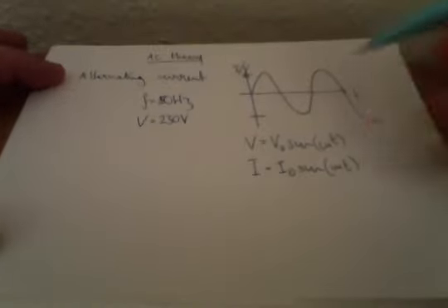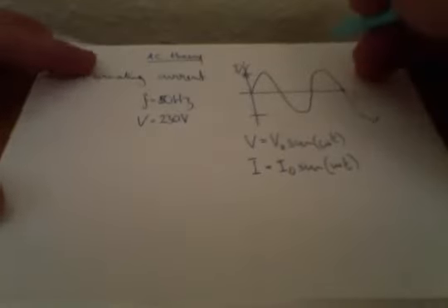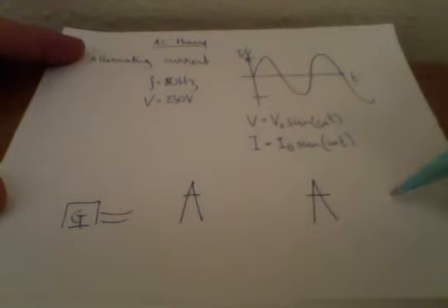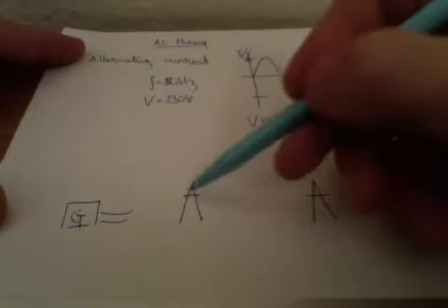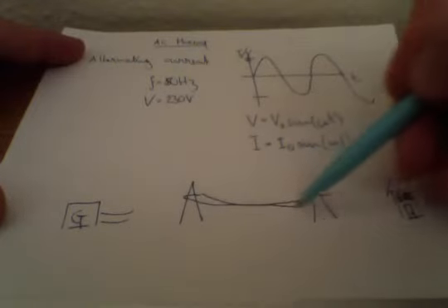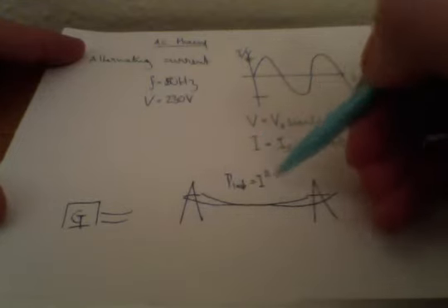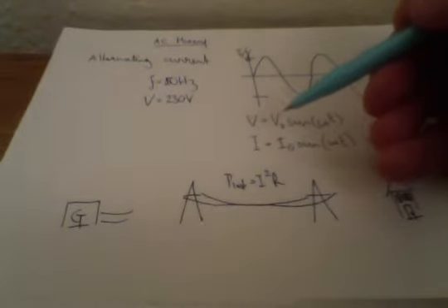Now there's a good reason as to why we have AC coming through, and I will quickly go through, now we have the facts down, why we use AC. Generators produce electricity for us, and then that's taken into the national grid, which carries, these are pylons by the way, the electricity through to our homes. Now we want to try and reduce the power loss in these cables, because these are huge distances they cover. And the power lost is going to be the current squared times by the resistance.